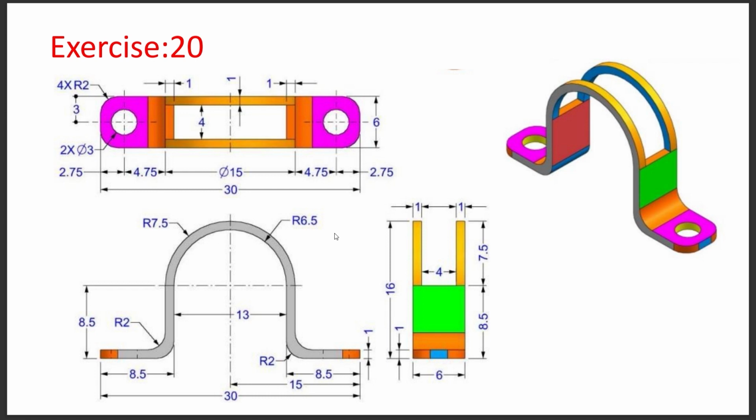And here in this case, one very important thing is, after making this initial sketch, if we make an offset distance of 1 mm, in that case we'll not have control over the second fillet, right? So we'll not complete the fillet part initially, we'll make the fillet part manually, right? So without wasting time, let us start our modeling using Autodesk Fusion 360.